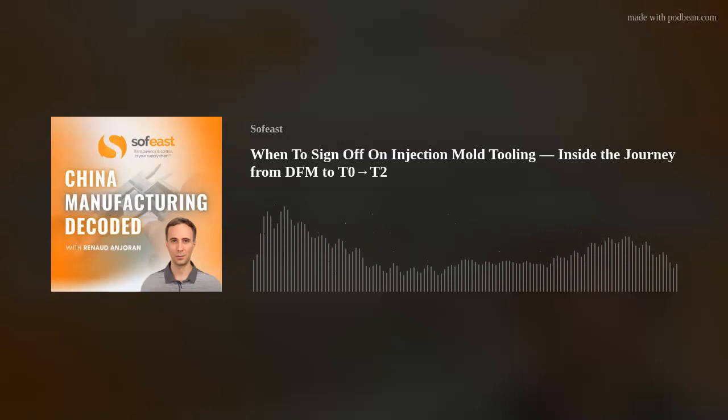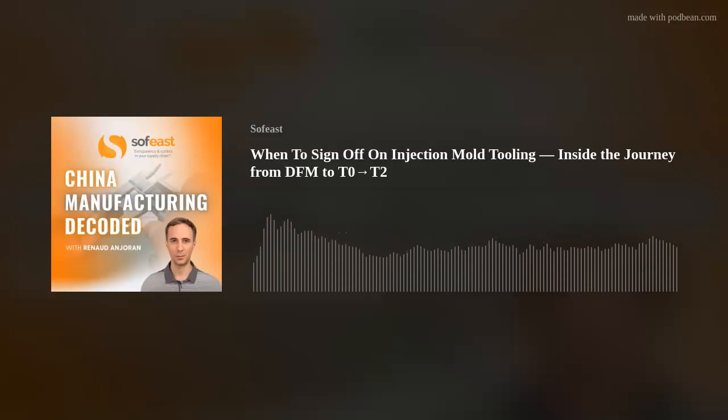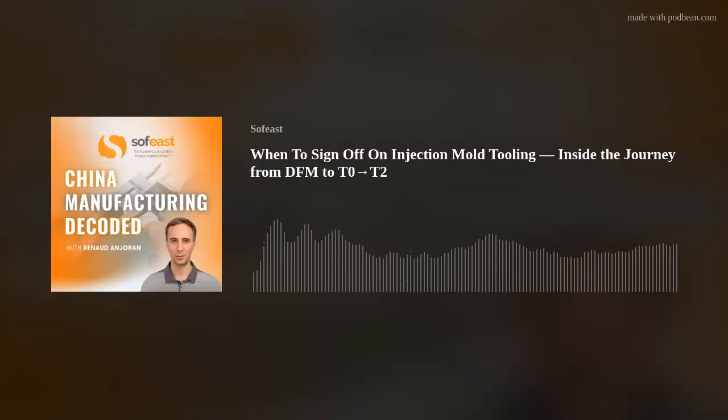All of the design work has been completed on the product itself. So take an individual part. An individual part needs to be tooled. The DFM will be looking at the wall thicknesses, the draft angles, the gate locations, the ejector placements, and areas that are really important from a visual aspect, in other words, the A surface and the B surface. What we don't want is ejector marks on the A surface, which is the aesthetically important side of the molded part itself.